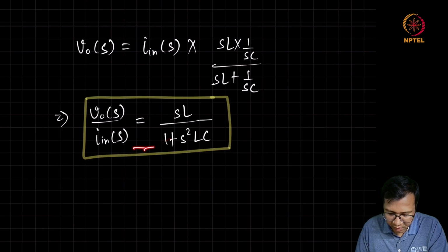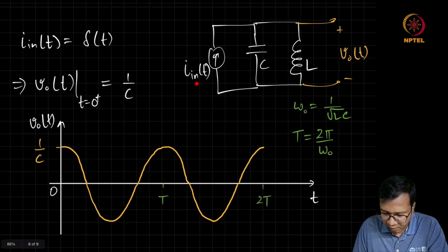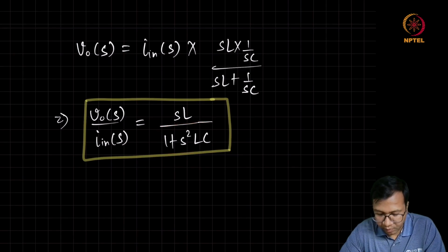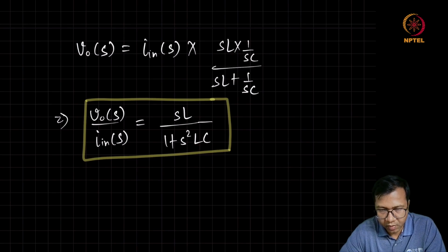So this is another way of looking at the same circuit, but now we have got a stimulus and an output. So now we are able to talk about this transfer function. We can see in this transfer function, the poles are completely imaginary. Because of these purely imaginary poles, we know that the impulse response is going to result in a sinusoidal output with constant envelope.